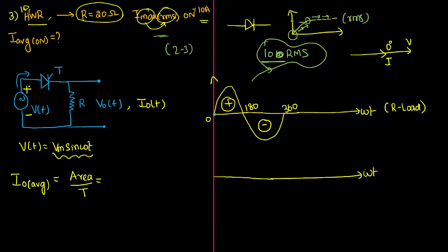So positive voltage will be applied across the anode, negative voltage across the cathode, but it is not a diode, it is a thyristor. Just by keeping positive voltage across the anode, we cannot turn on the SCR. It is very important to give the firing angle. Firing angle means we must inject the gate current. That gate current must be injected at a particular angle or particular time. We saw some questions, I hope you all remember them from the previous sections.